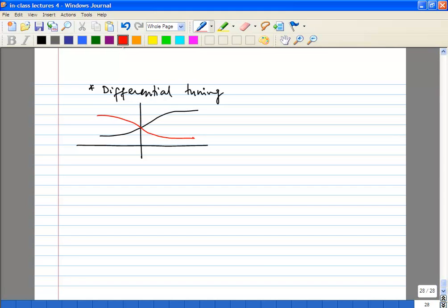That is definitely possible, because whether you take an NMOS or a PMOS varactor, you will have different curves. So you can exploit this to get a wider linear range for your control voltage.